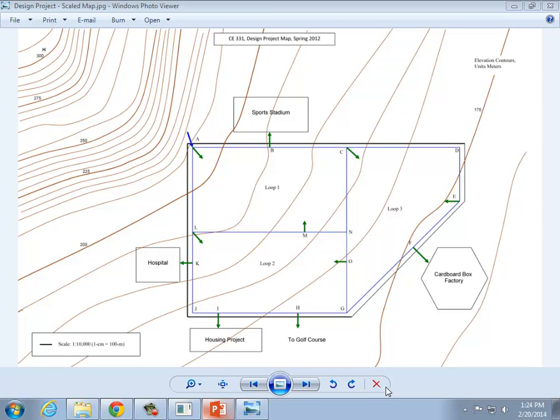So this project goes through in a couple of different phases. The first thing you're going to do is demand forecasting. I've made assignments that I'm going to hand out in a second, but you'll go through the second to last page and look for your name. For example, Andrew has Reno. Each of you has been assigned a city, and then there's a series of assumptions I want you to make about the population density inside of the city, the fire flows that are needed in case there was a fire that the fire department was going to be taking water out of the pipe network to fight.